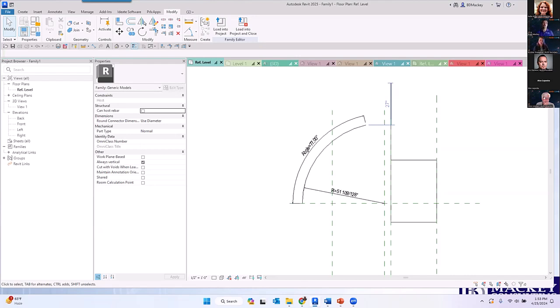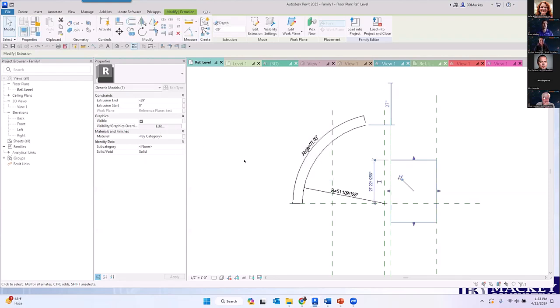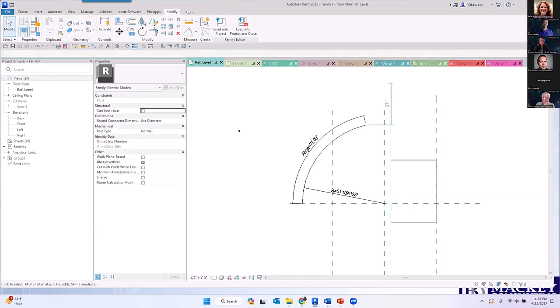It was just something you had for geometry purposes. Yes, you can do the IFC in and out and back and forth. I've seen some people do it as a DWG, as long as the DWG is okay. A lot of different workflows in that, but you will lose all parameters or all associativity to that, including the fact that, oh, gee, this might have been on a subcategory. I didn't talk about the visibility that was set up, any of that stuff. It's all gone. Material parameters, all of that stuff, gone. So it gives you the geometry, but it doesn't give you a Revit family.